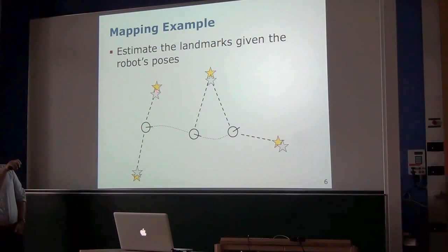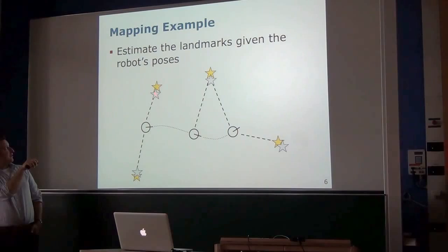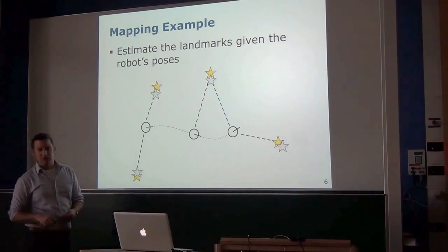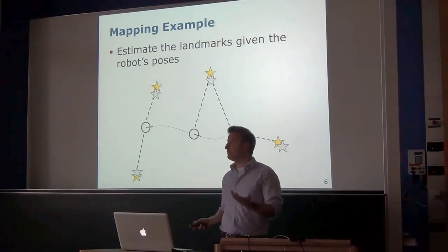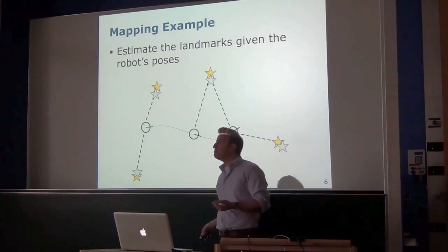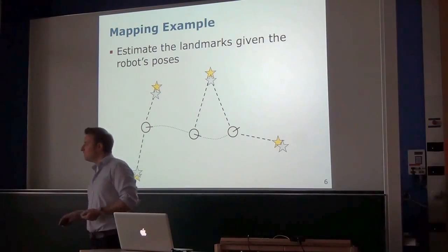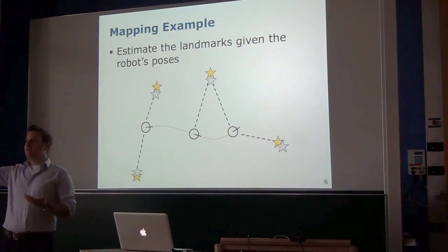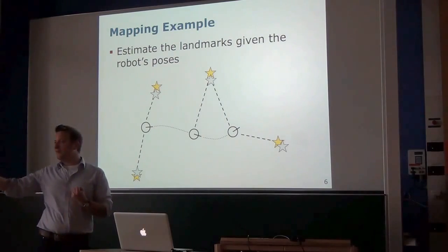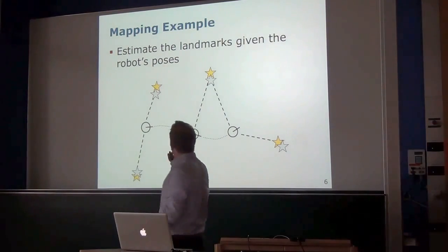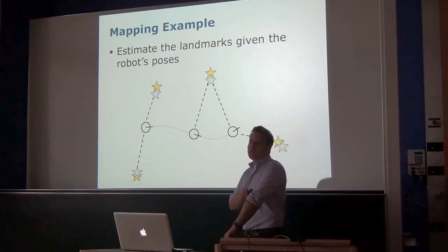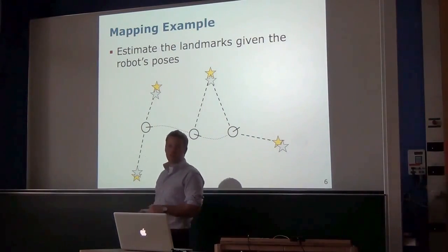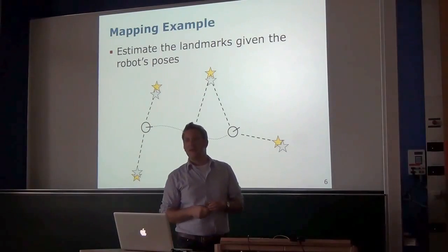Those guys don't fit perfectly, so these landmarks, the gray one is the observed, what the robot thinks the landmark is, so gray is the estimate, and yellow is where the landmark is in reality. And the reason is that your sensor typically has errors, so no sensor is perfect. If you measure the distance to the tree, you may say this tree outside there is now 30 meters away from me, but in reality it's 31 meters away. So there are always errors in the observation. And therefore, those landmarks are not perfectly at the location where you think they are. Typically, the more money you invest into your sensors, the better those estimates get, but they are typically not perfect.